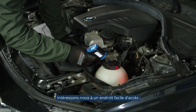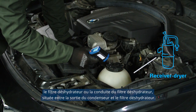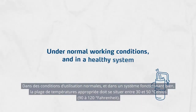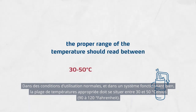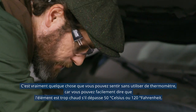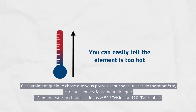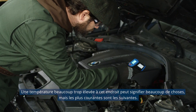Let's have a look at one spot that's easy to access: the receiver dryer, or the line to the receiver dryer that's between the condenser outlet and the receiver dryer. Under normal working conditions and in a healthy system, the proper range of the temperature should read between 30 to 50 degrees Celsius or 90 to 120 degrees Fahrenheit. This is actually something you can sense without a thermometer because you can easily tell the element is too hot if it's above 50 degrees Celsius or 120 degrees Fahrenheit. A temperature that is way too high at this spot can mean many things, but here are the most common.